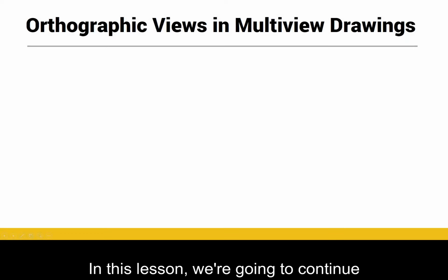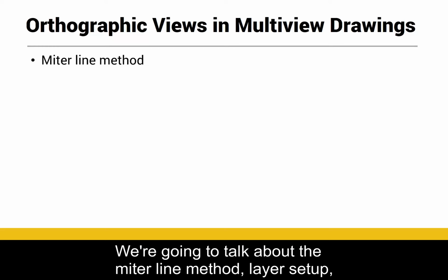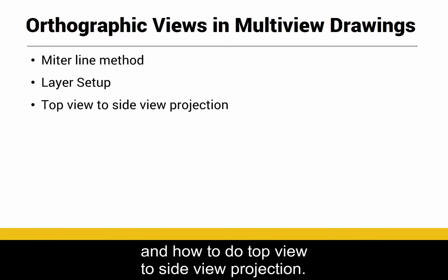In this lesson, we're going to continue talking about orthographic views in multi-view drawing. We're going to talk about the miter line method, layer setup, and how to do top view to side view projection.